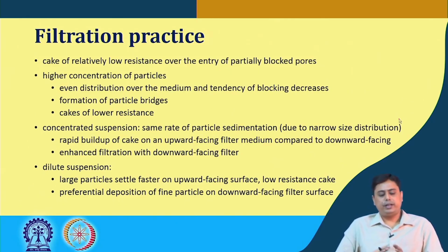Also, sometimes with a concentrated suspension, the size ranges are not very wide. There is a narrow size distribution of the particles, which means that if they are settling rapidly, the sedimentation rate is the same for all, because the size range is narrower. All the particles will try to sediment at a similar time, which means there will be a rapid build-up of cake if the filter surface is facing upward.